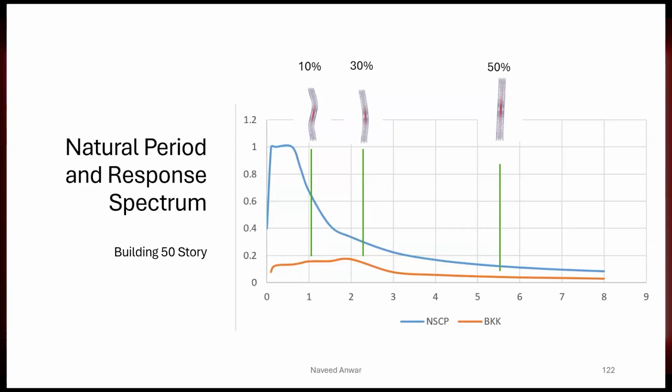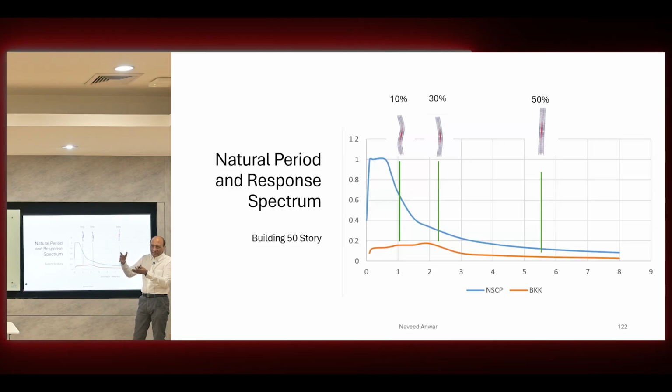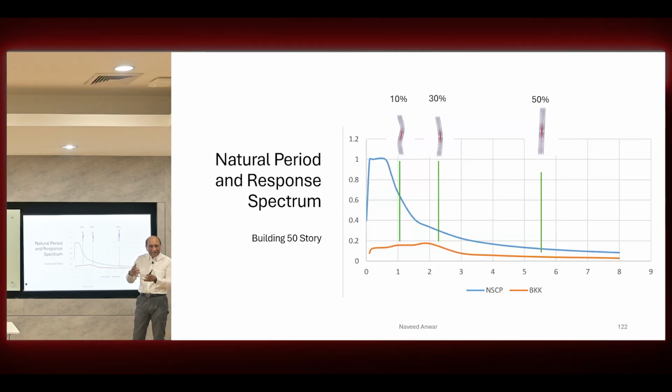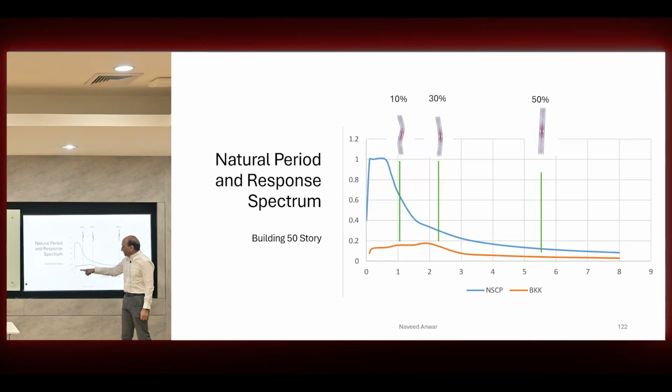This is because the rock is very far below the soil, so there is a basin effect. Because of that, the first period starts later, since the soil is already there. The soil period also needs to be added before we reach the structure. That soil is also moving slowly, and the natural period of the soil between the rock and the structure creates this effect. So this is the response spectrum.